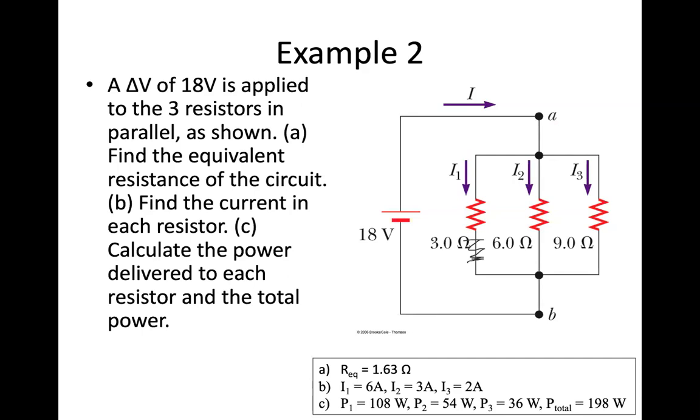I would say, hey, the bottom side of this makeshift resistor, sure, it can flow to point B. But the top side of it, oh, it's going to hit another element along the way. It cannot flow uninterrupted. So sometimes it's not going to be visually obvious, and it's important to check. Do all of their top sides flow uninterrupted to the same place? Do all of their bottom sides flow uninterrupted to the same place? If the answer is yes, then they're in parallel.